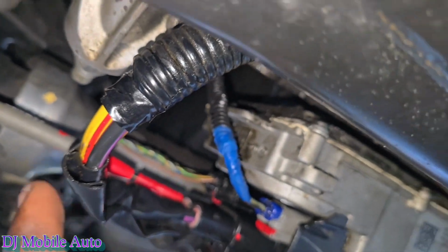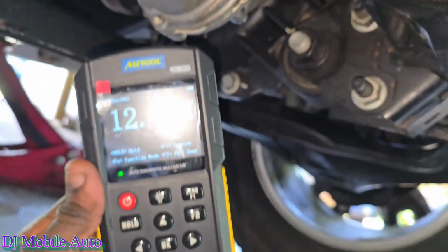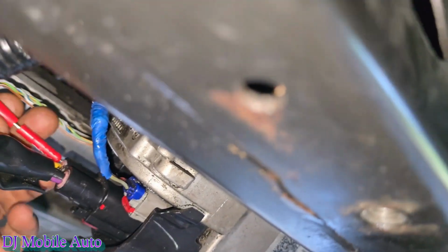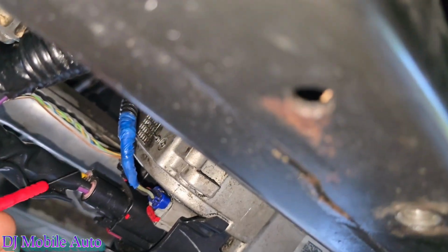So that cable that we saw on top, which was the yellow with the red stripe, I'm expecting to see 12 volts there, and I am right here now seeing 12 volts. So that's coming off that 125 amp fuse. Alright, so I'm gonna go on to the black with the purple stripe.